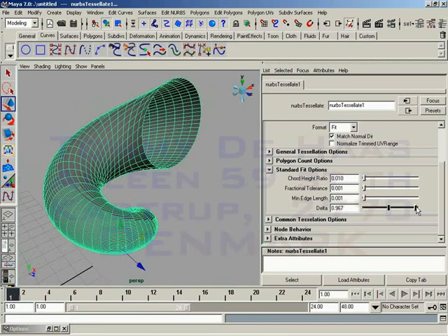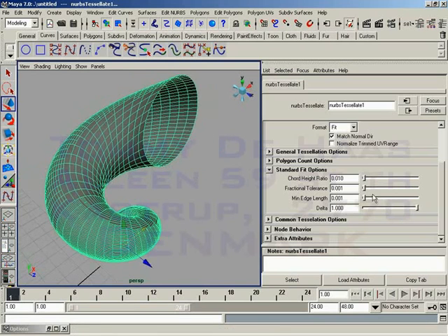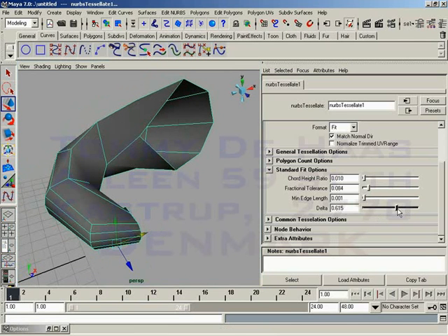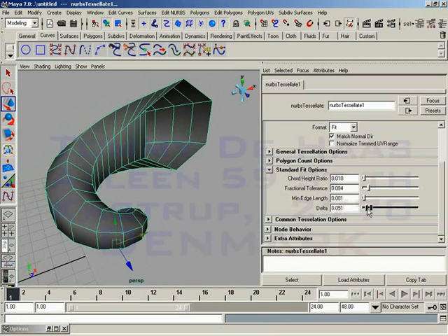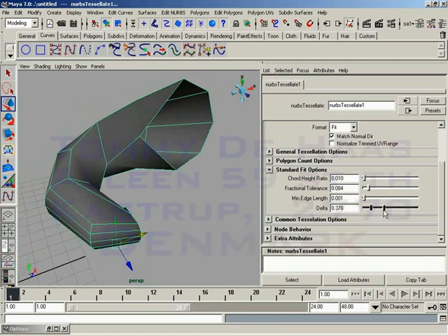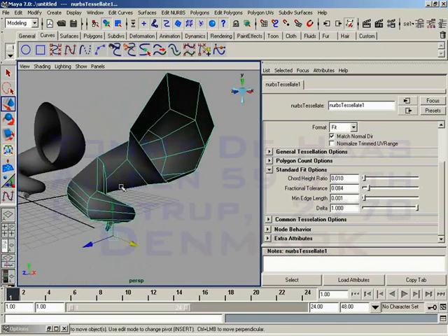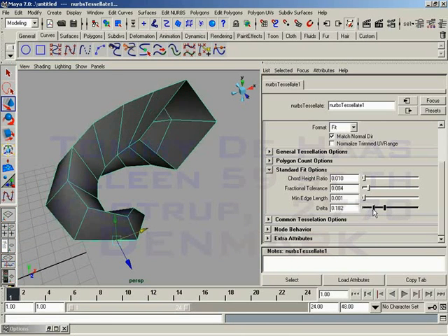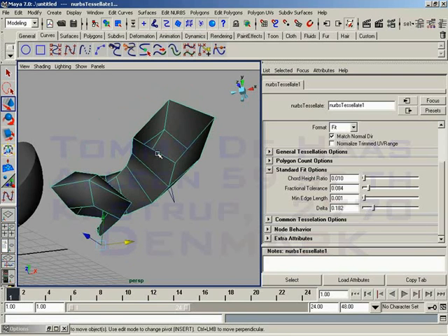As you increase the delta, you're actually increasing the space. Here you go, this should be a nice example. You're increasing the spacing of this grid. So the lower you go, the more tessellation you get because that grid spacing is lower. The higher you go, the less tessellation you get because that initial grid has wider grid spaces. So it's kind of the basis. It's where all of the tessellation in this case is going to begin.